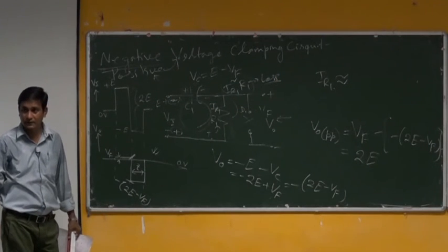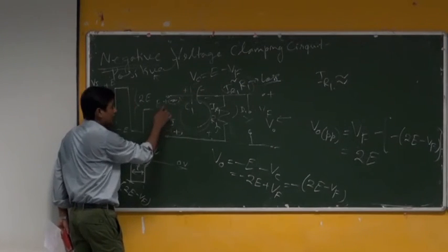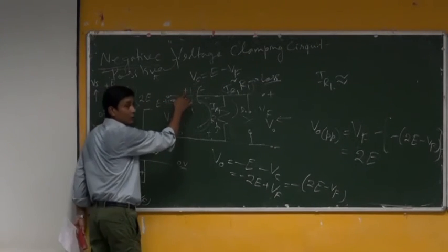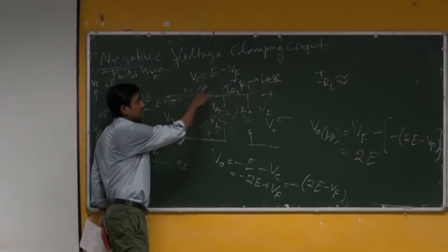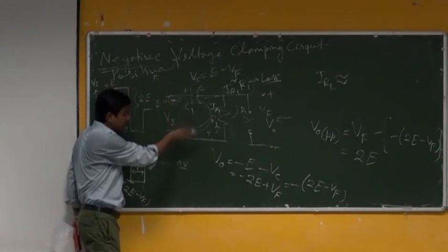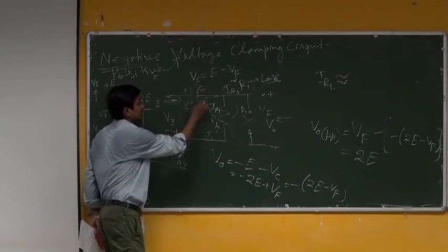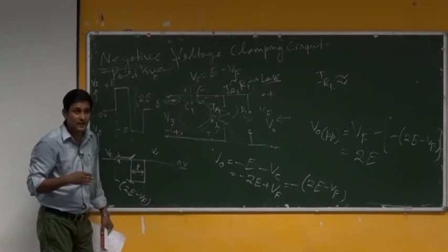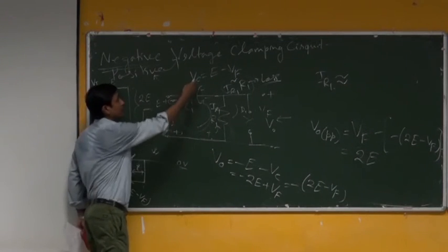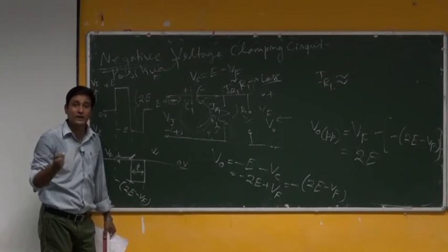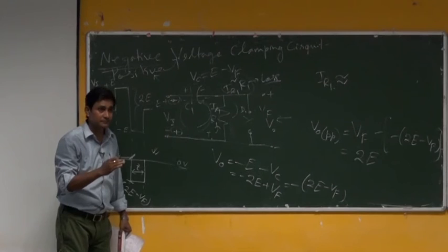Not only that, earlier you were driving this capacitor with a potential where positive here, negative here. That's why it was getting charged with positive this side, negative this side. Now you are charging it the other way. So you are actually forcing it to get positive charges accumulated here and negative on the other side, because you are dominating it with another potential where E may be much greater than the earlier Vc stored there.